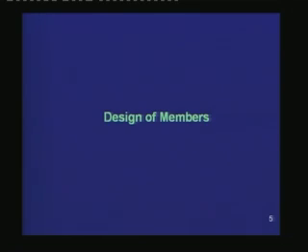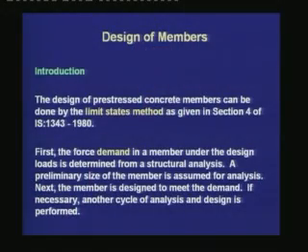First, we shall study the design of members, some general ideas. For design of prestressed concrete members, we follow the limit states method as given in section 4 of IS 1343/1980. First, the force demand in a member under the design loads is determined from a structural analysis. A preliminary size of the member is assumed for analysis. Next, the member is designed to meet the demand. If necessary, another cycle of analysis and design is performed.